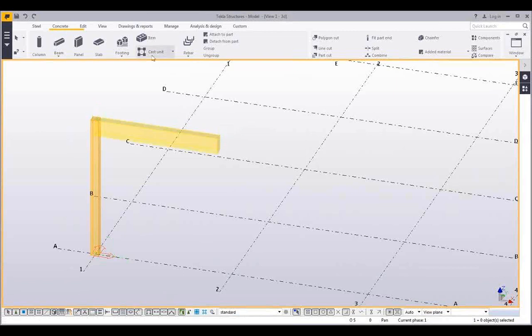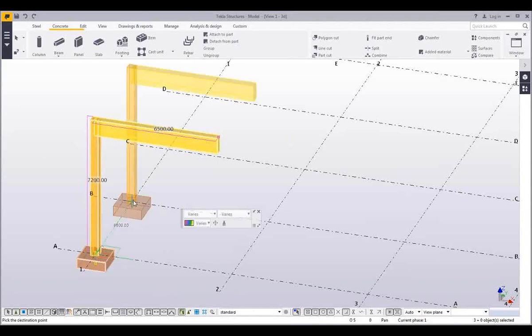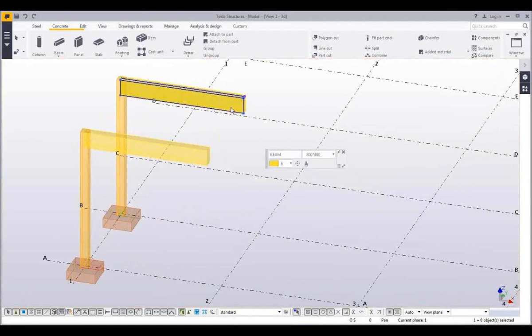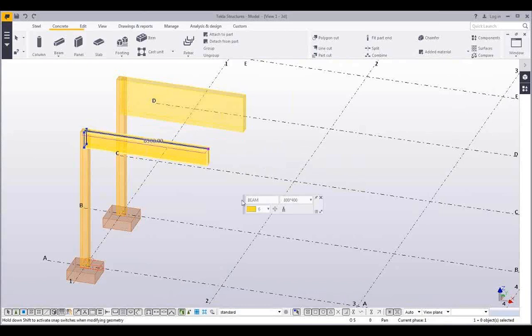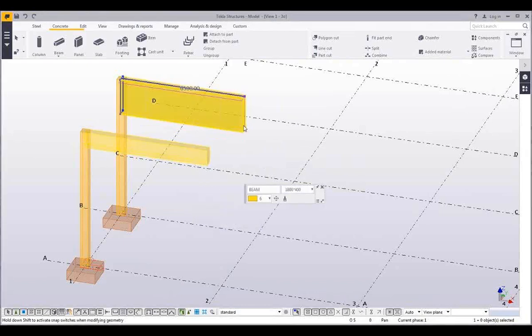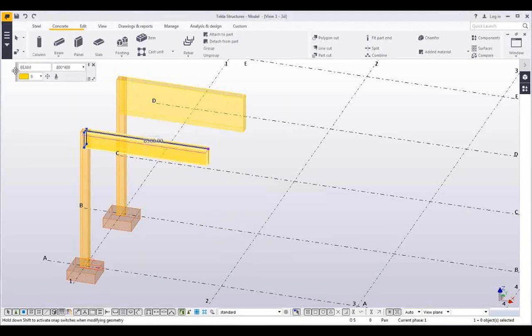The best thing in the ribbon, compared to the icons in the old user interface, is that the icons don't jump around anymore. Icons will stay in the order that has been set. You can also see the new contextual toolbar that combines the direct modification toolbar and the mini toolbar. You can set the toolbar's relative location by dragging while holding the control button. You can also pin the location of the toolbar.